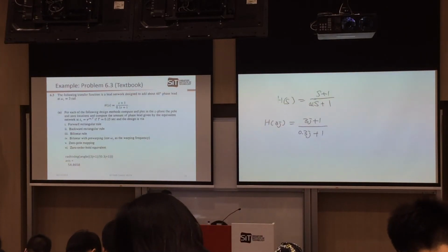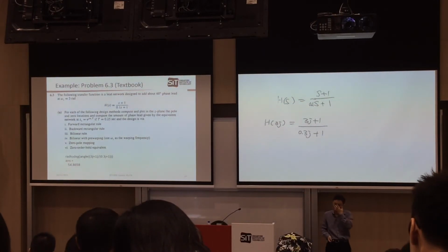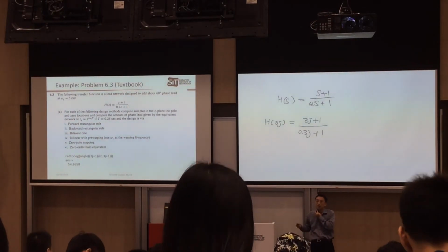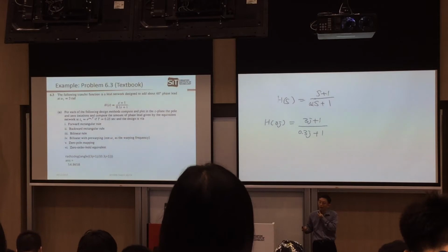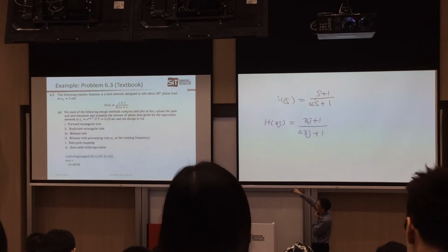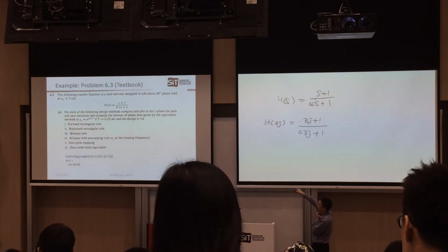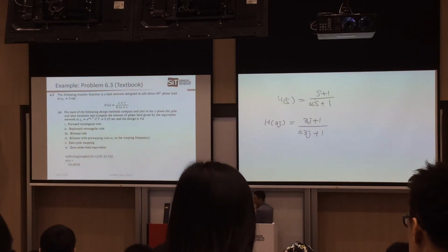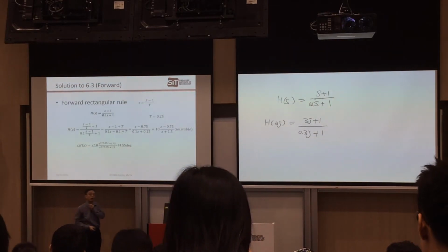Okay. That's why we have to note this down, because we use this one as a reference to see how good the equivalence is. Because we want to find out whether the digital controller achieves similar functionality to your original designed analog controller, right? So if it's a continuous or analog controller, you are supposed to get your phase angle compensated by about 54.86 degrees. So it's close to 60 degrees, not exactly 60.